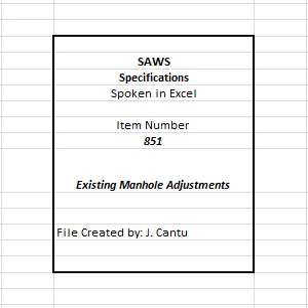851.5 Construction. Manholes shall be lowered below street subgrade before placing base materials, and openings shall be protected by temporary hatch covers. 1. Manholes adjusted in non-paved areas shall be set per proposed final grade. 2. All manholes requiring adjustments beyond the maximum or minimum number of throat rings, described herein, shall be subject to specification item number 855, existing manhole reconstruction.